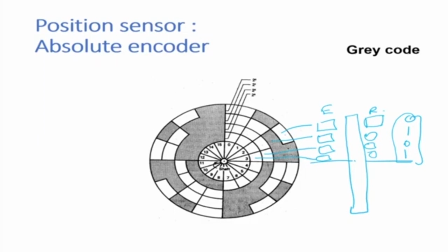Why? If you look at these sectors, this could be 0, 0, 0, 1. This could be 0, 0, 1, 0. That way, each of these sectors, either this one, this one, this one, are unique here. So the 4 bits that are going to come are going to be unique. So simply by looking at those bits, the controller can know where it is now.